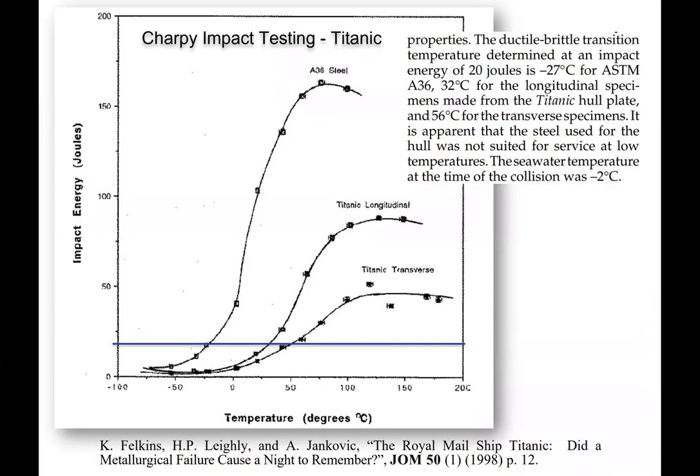So here's what the data looks like that comes out of the Charpy impact tester. If you've watched the video, they've explained exactly how this impact energy is measured, so again, you want to watch that video. But this impact energy is the energy required to cause failure in the sample. How much energy did that sample absorb during the failure process? The higher energies would be your ductile samples, and very low energies would be brittle.